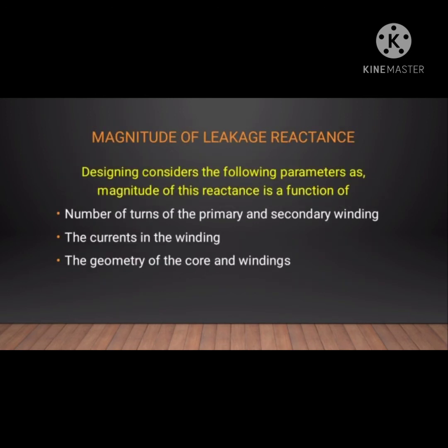Next is the magnitude of leakage reactance. Designing considers the following parameters, as the magnitude of this reactance is a function of them. So, sa pag-design natin, we consider the following parameters: yun nga yung number of turns of the primary and secondary winding, the current in the winding, and the geometry of the core and windings.